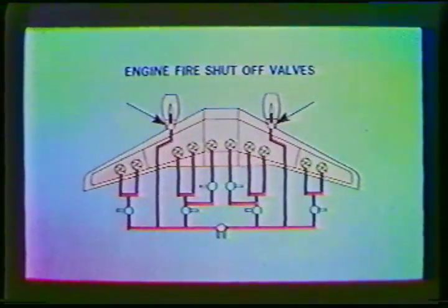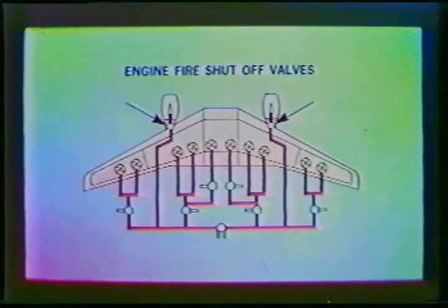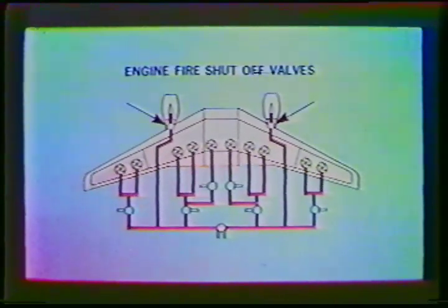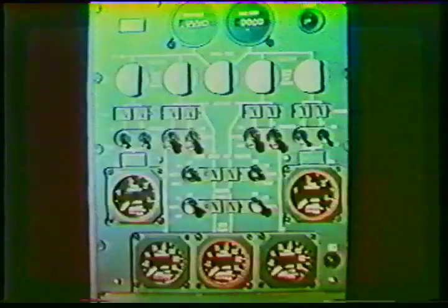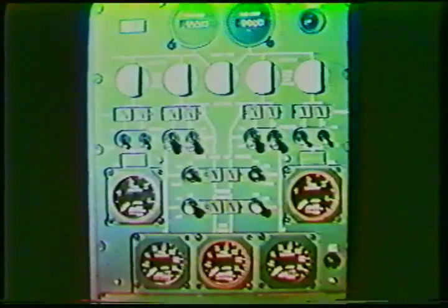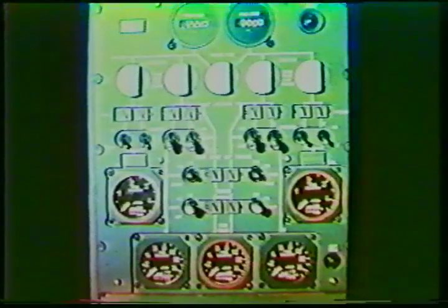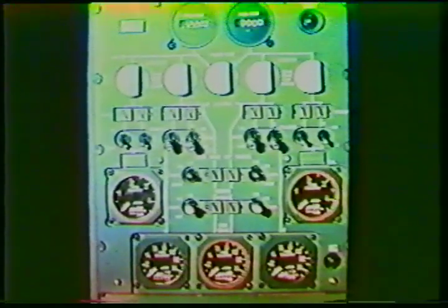2 fire shutoff valves allow the fuel supply to the engines to be stopped. The 2 fire shutoff valves are mechanically controlled through cables by the corresponding engine fire handles located on the overhead switch panel. The fuel flow is clearly displayed on the fuel control panel. Just remember to direct your scan from bottom to top.